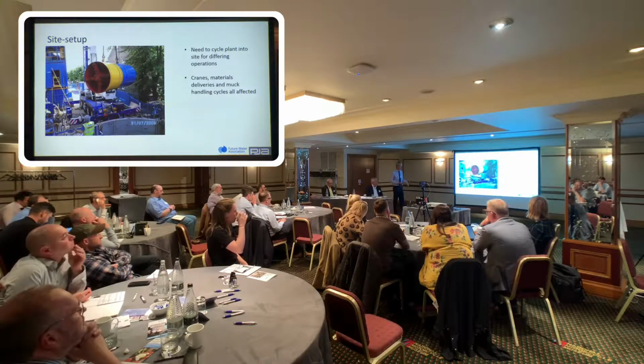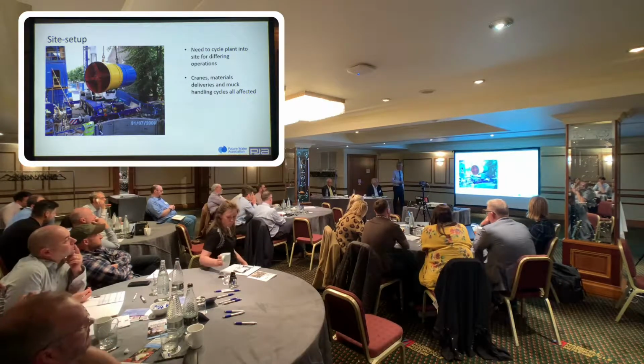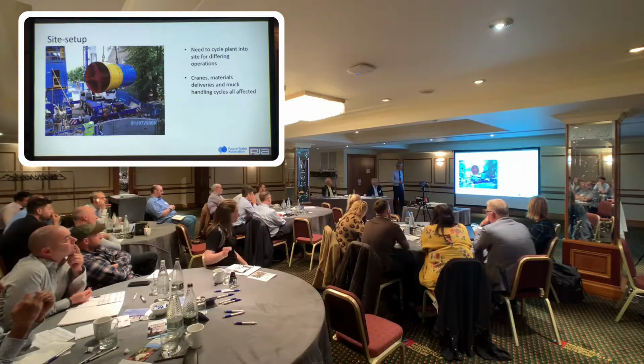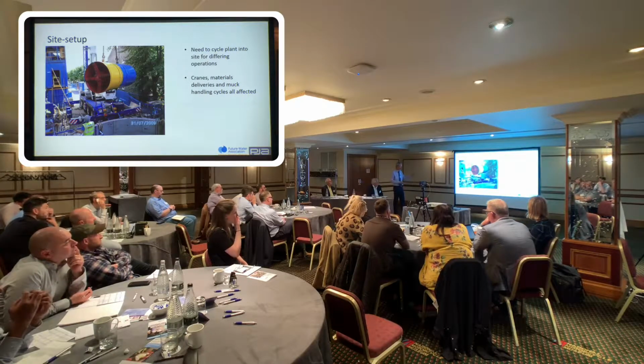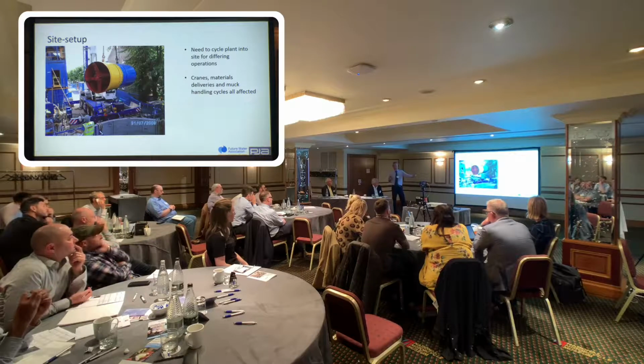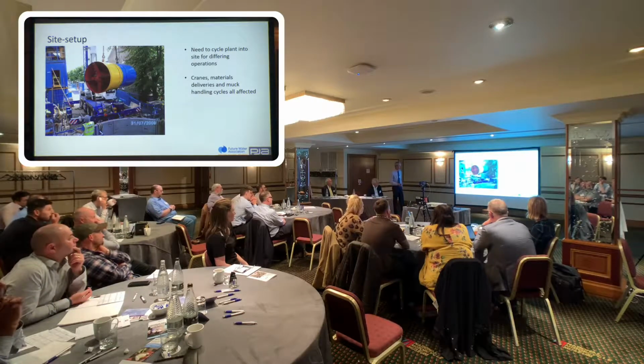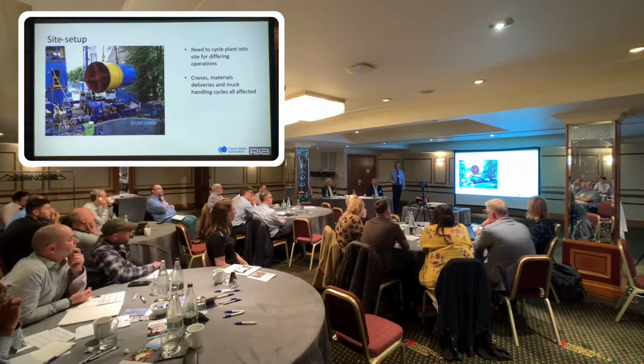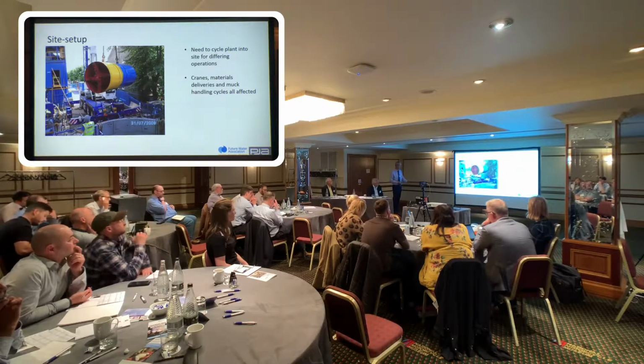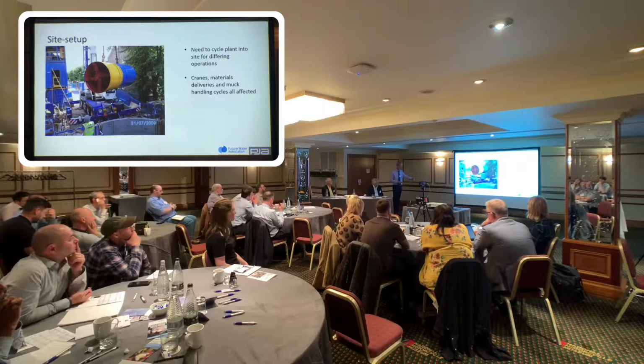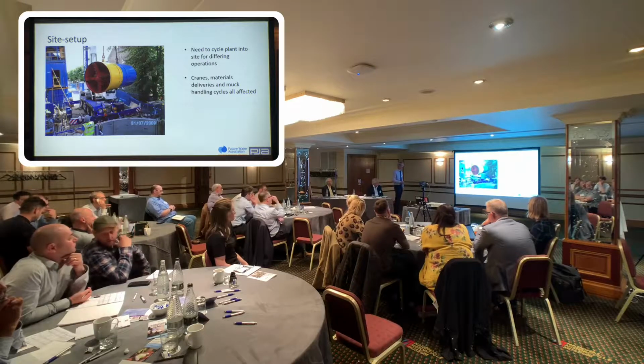This is the same site. In order to get the machine down the hole, we need to bring in a much bigger crane, which means that access has to be cleared before we can drop the machine. Then that crane goes away and the next crane comes in. So you're constantly cycling equipment in and out of the site, which has program implications, obviously, and might mean that you don't get quite the same kind of production in a confined site as you might elsewhere.